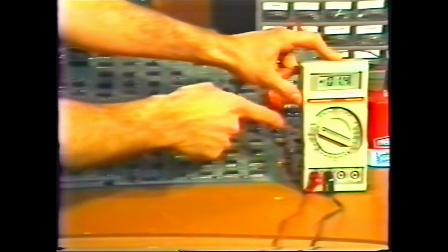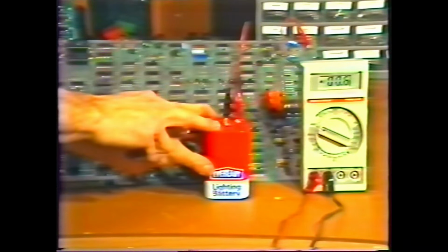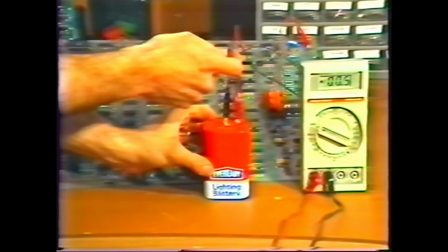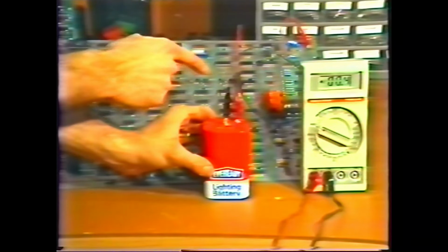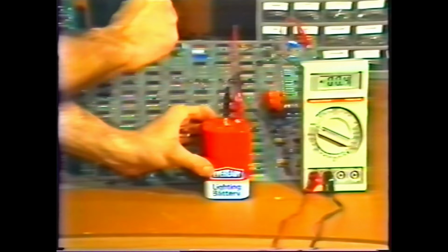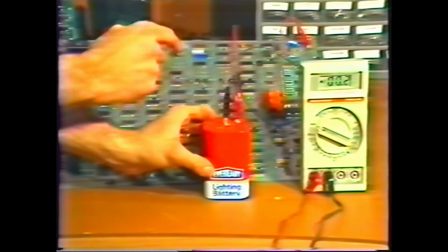We can't find it with our meter set on resistance, but we can find the short if we move our meter selector to read voltage on the lowest DC range. Connect a battery to the power rails. Connect the ground lead to the ground test point and the red lead, which is connected to the positive terminal, to the 5-volt test point on the printed circuit board. What we're trying to do here is power the shorted board with the battery. Then take the meter and connect the meter leads to each individual power rail one at a time.